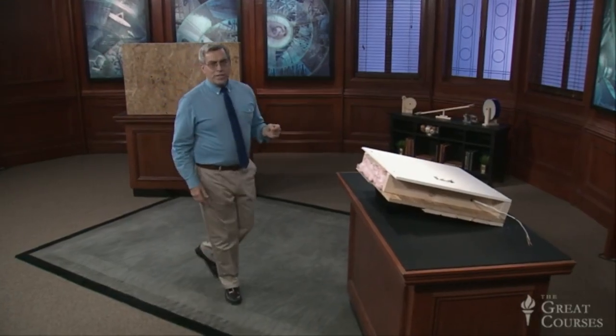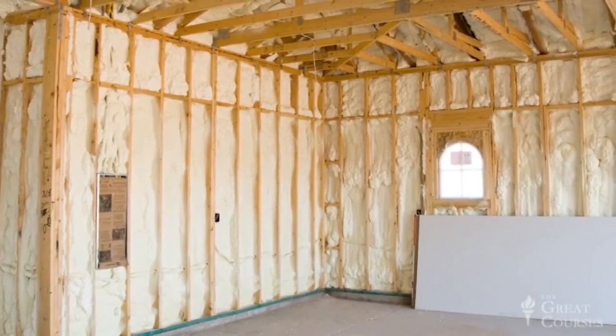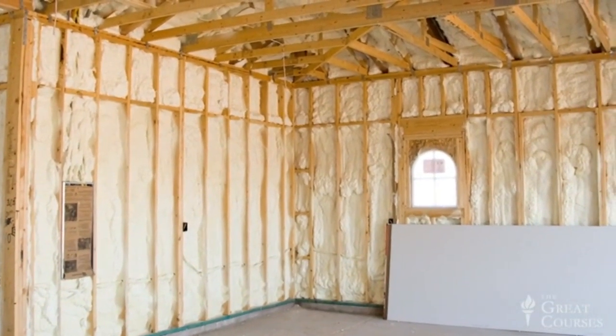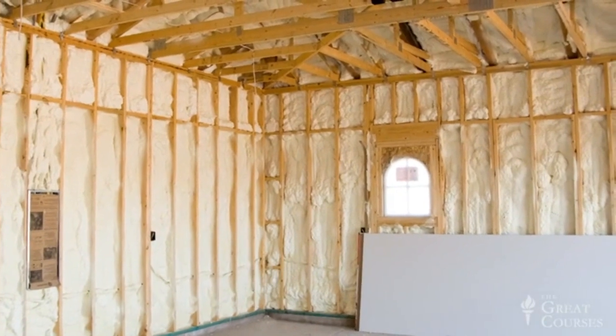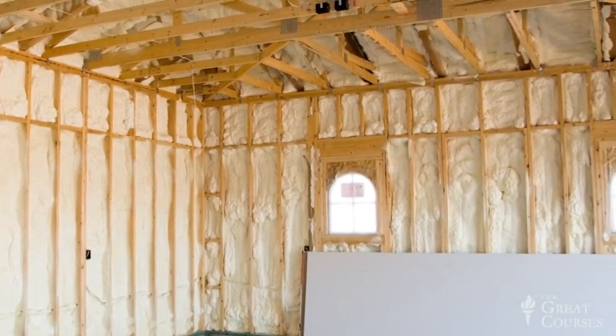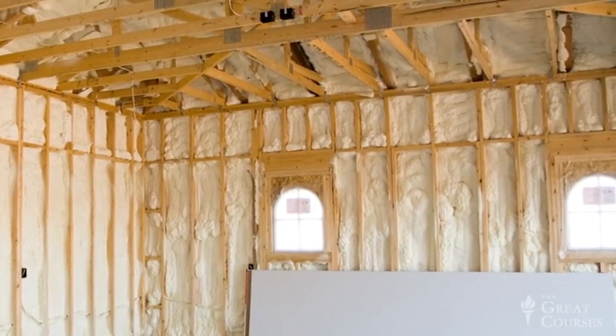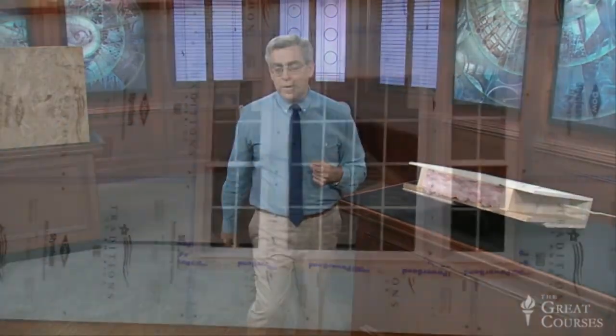Today, builders are addressing this challenge in a variety of creative ways. One approach is simply to use higher performing insulation, like urethane foam, for example, within the wall cavities. This approach doesn't directly address the thermal bridging problem, but because the cavity accounts for about 3/4 of the wall area, insulating the cavity more effectively can push the overall R value high enough to meet the code.